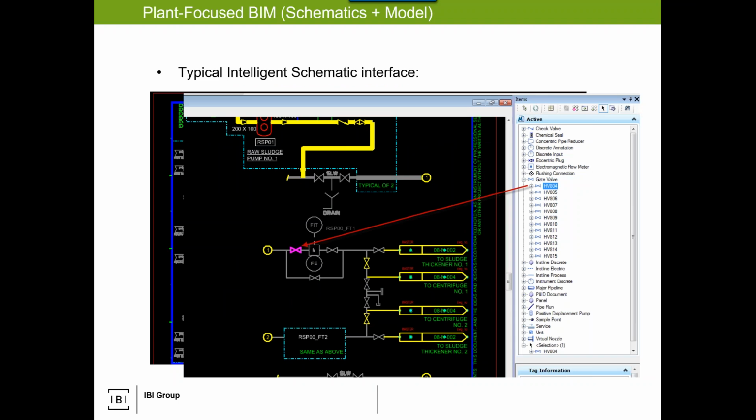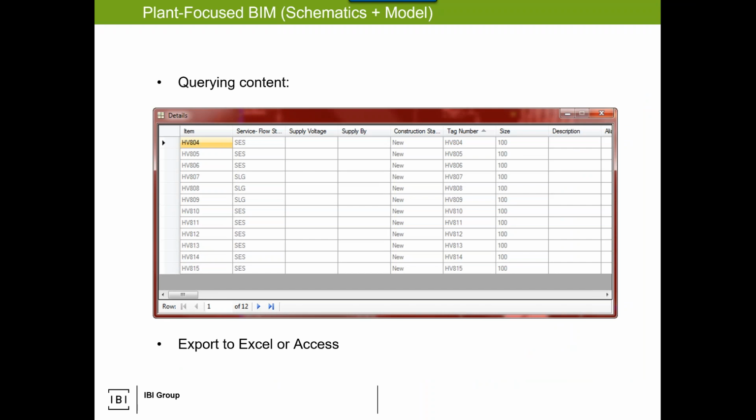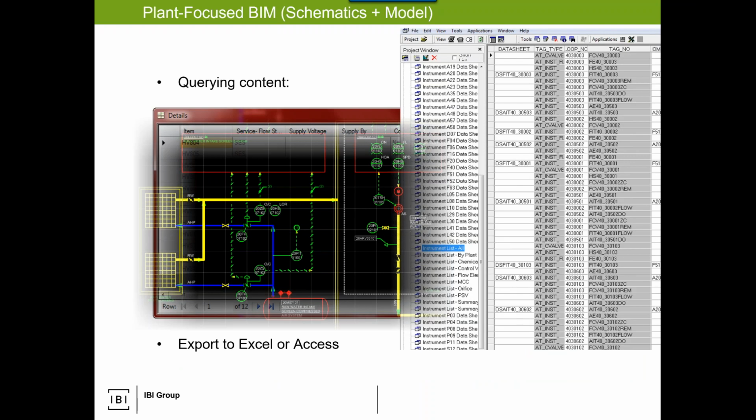So this is a P&ID, a process instrumentation diagram. And in the P&ID, it allows us to show all the varying assets. These are all the valves, pipelines, major pieces of equipment. And I think I described in previous weeks, this flow here that I'm showing in the middle of the screen, that could span multiple buildings, maybe even multiple sites. But the flow is represented in a schematic. We can query it all and then analyze it, tie it to an asset management system, and importantly, tie it back to the plant model.